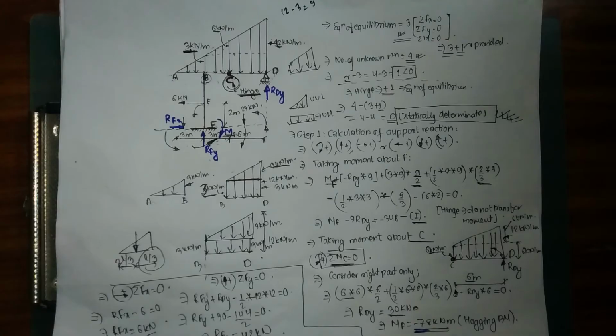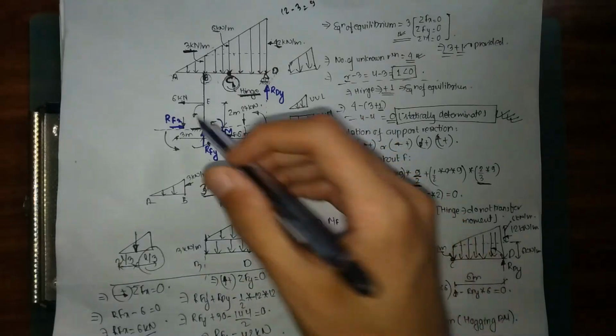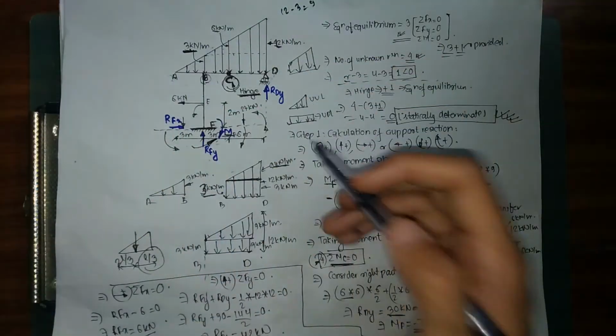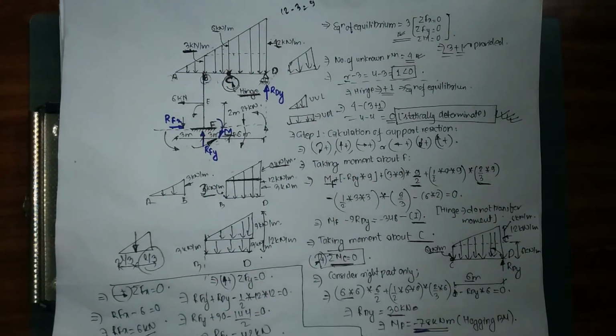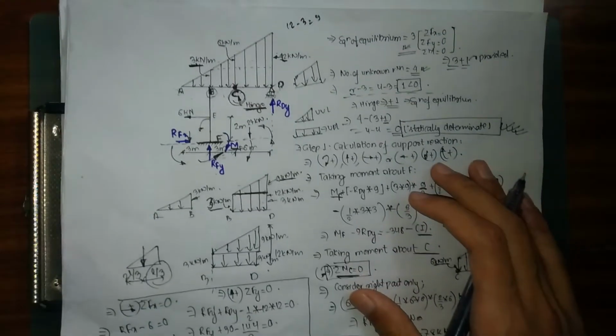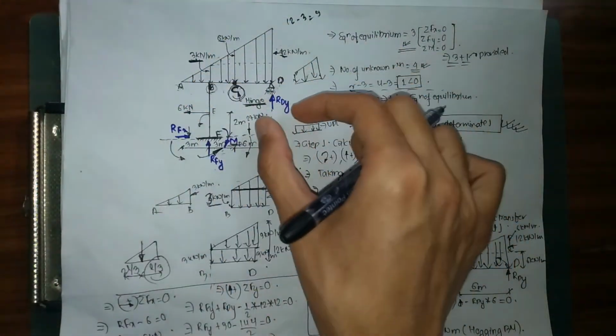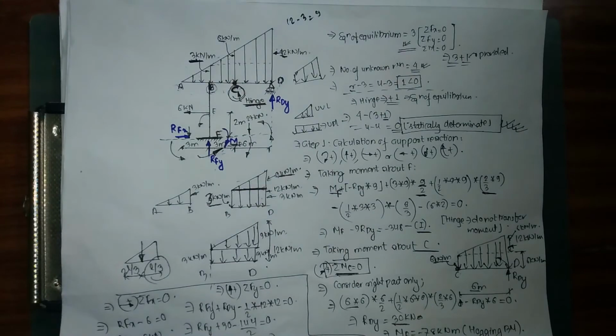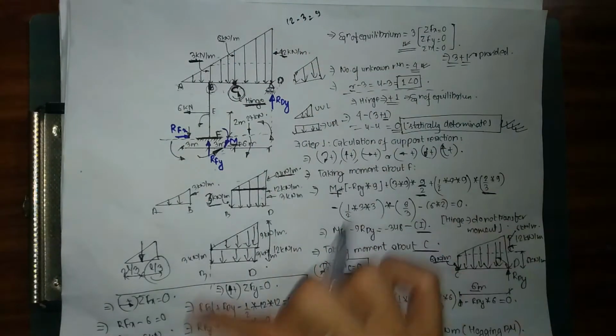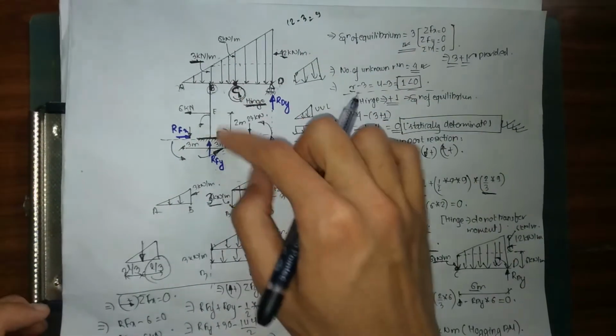I did not say this before in the video, but right now we're considering our overall frame to be in equilibrium. Since our overall frame is in equilibrium, each and every member, member BF, member AB and member BD, also must be in equilibrium. So right now we're going to consider equilibrium of member BF.